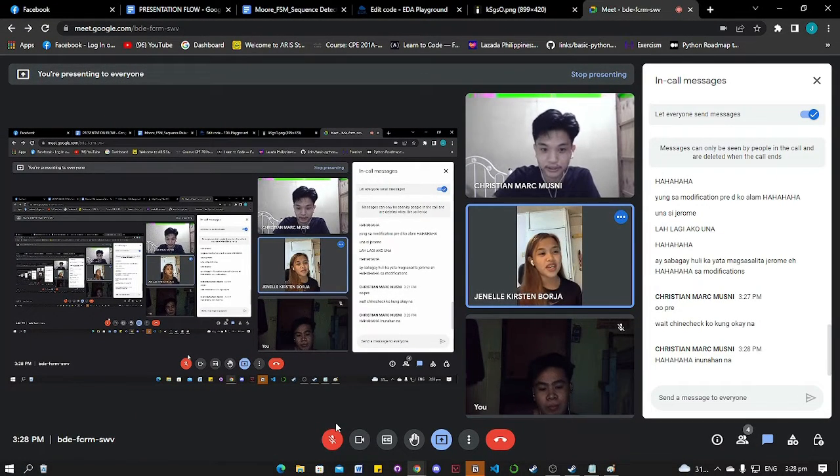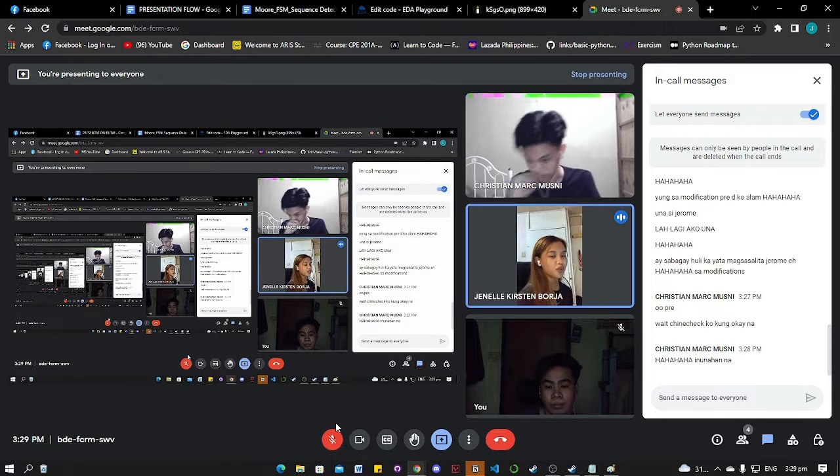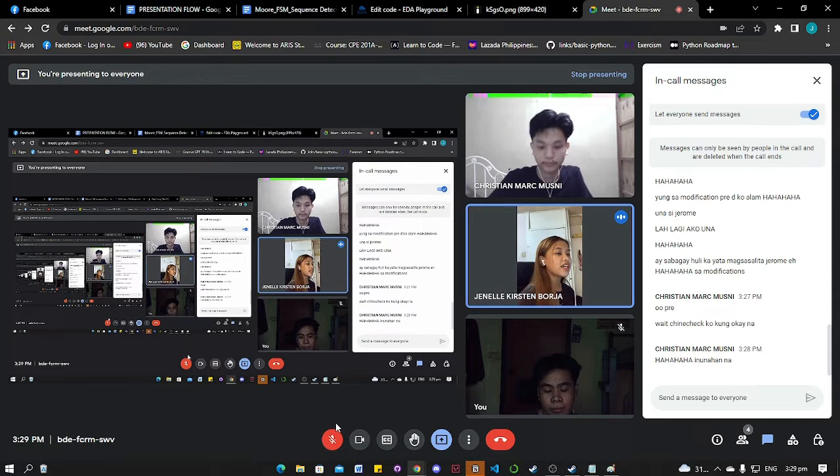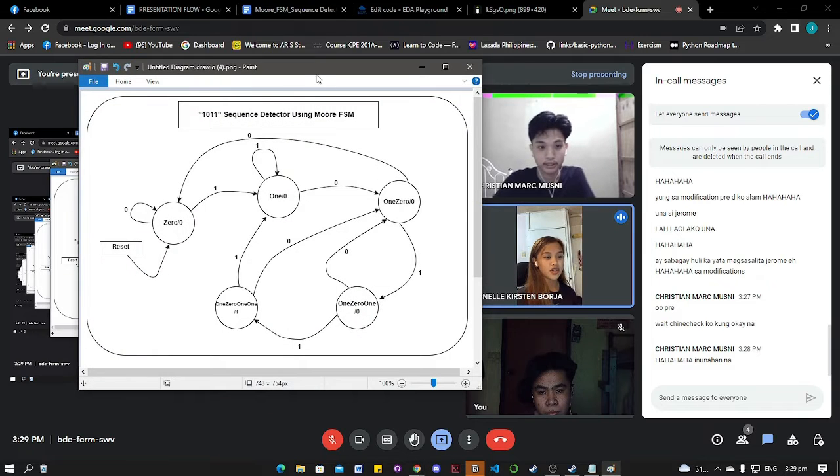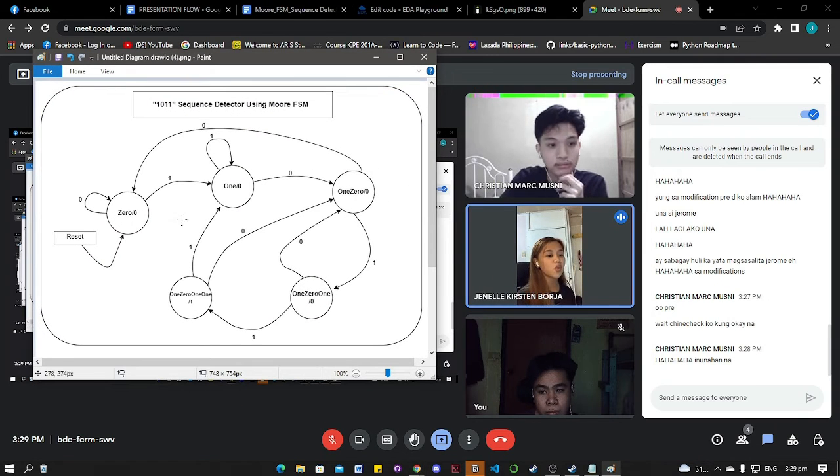This is Group 4, and today we're going to tackle the project titled Moore FSM Sequence Detector. But before that, let me first give you a brief introduction of what it is all about. The 1011 Moore FSM sequence contains 5 total states: the 0, 1, 10, 101, and 1011.